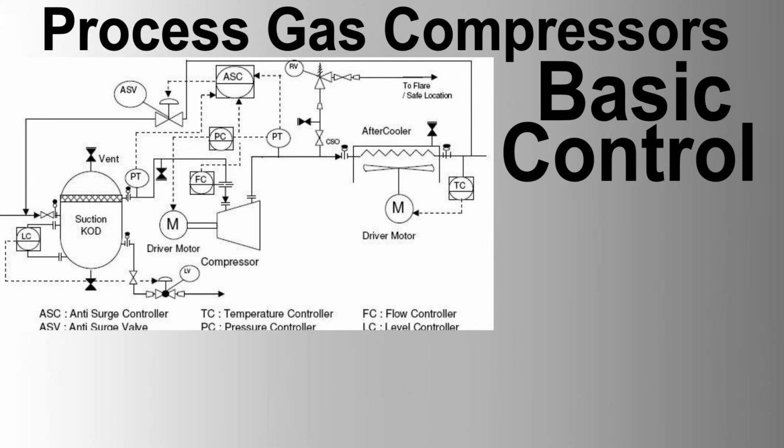#3 Instrumentation and control system integration. A. Control system architecture. Expand the distributed control system, DCS, or programmable logic controller, PLC, to accommodate the new compressor. Ensure the control architecture supports seamless integration of the new compressor's control loops.